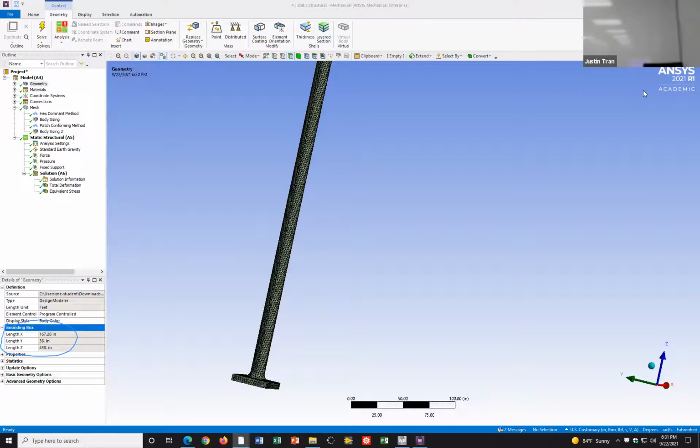So if you click on mesh right there, actually under quality, yeah, this right here. If you look at mesh metrics, click on that. You can change that. There's a lot of metrics for quality. And so let's change it to skewness.